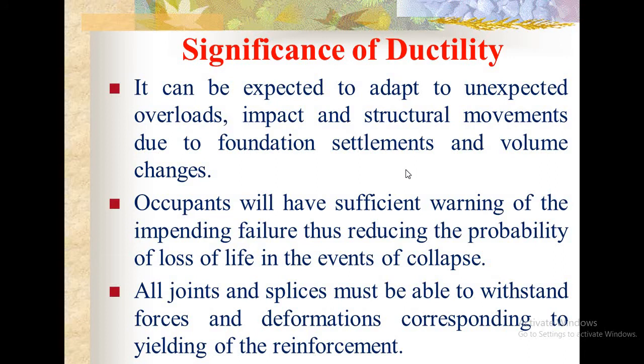Then see, what is the significance of ductility? It can be expected to adapt to unexpected overloads, impact and structural movements due to foundation settlement and volume changes. Occupants will have sufficient warning of the impending failure, thus reducing the probability of loss of life in the event of collapse. All joints and splices must be able to withstand forces and deformations corresponding to yielding of the reinforcement.